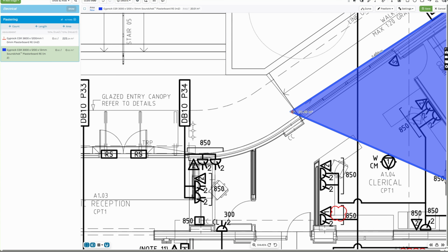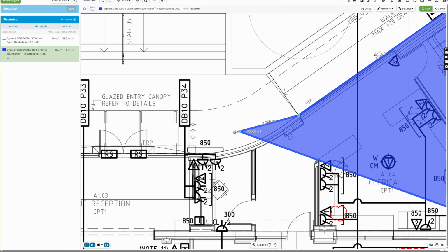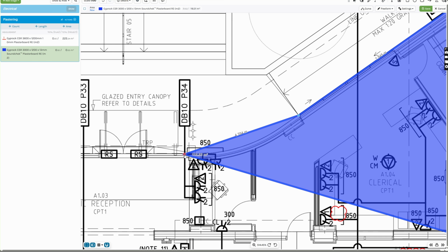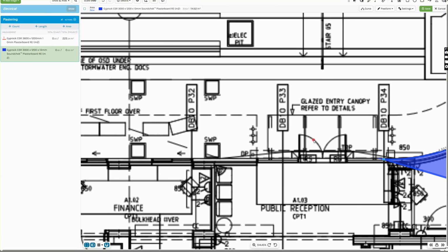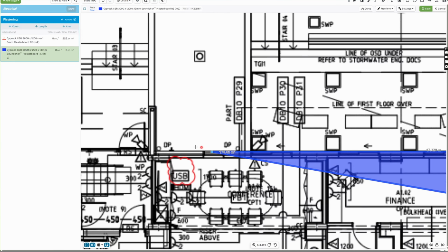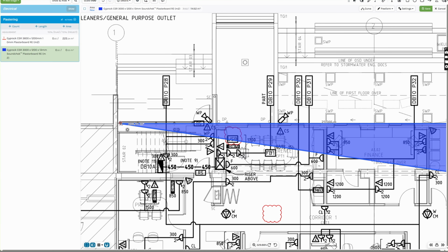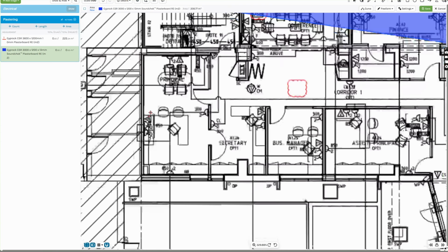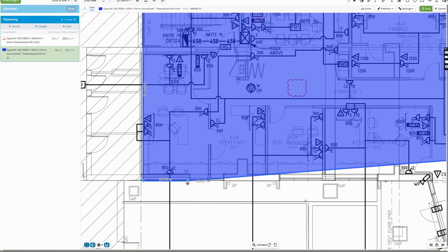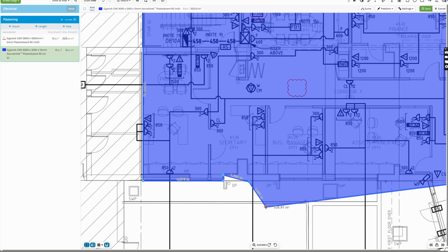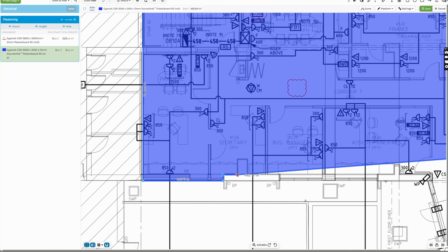We've come to another curve again, so we're going to click on one side of the curve, jump across to the other side, press W for Whiskey on our keyboard again, move that mouse back and drop that point into place. So your shortcut keys here for your lengths and areas are completely the same. So you're clicking to change direction, you're holding shift for that straight line. If I put a point in the wrong place for any reason, oh whoops, that doesn't go there, I'm holding control on my keyboard, command on a Mac, tapping Z for Zulu, and that just undoes the point. And we can just really easily go around the outside of this building.